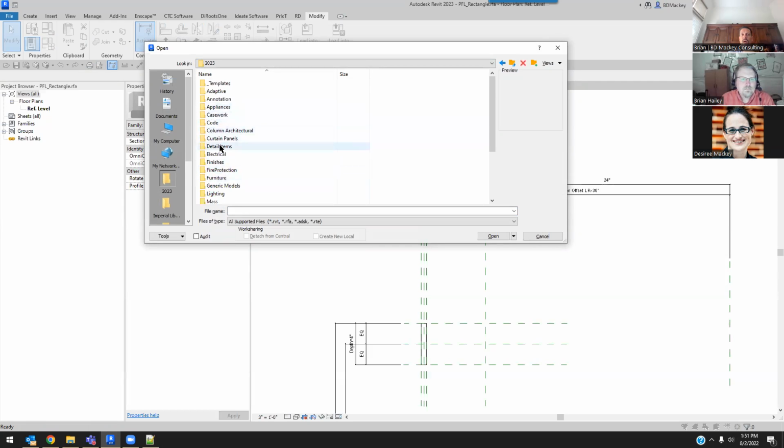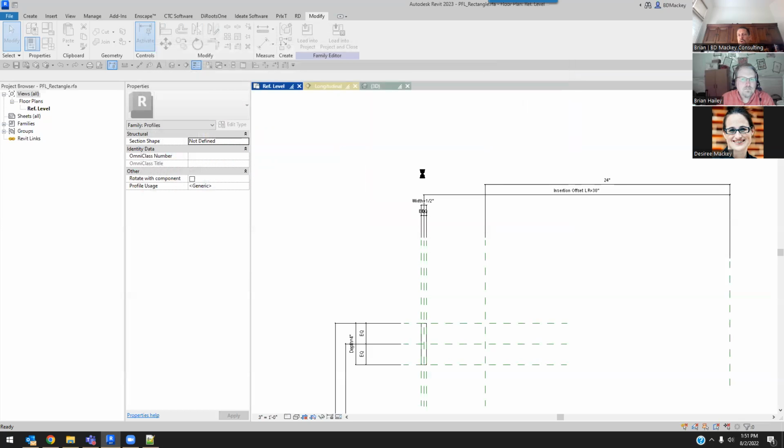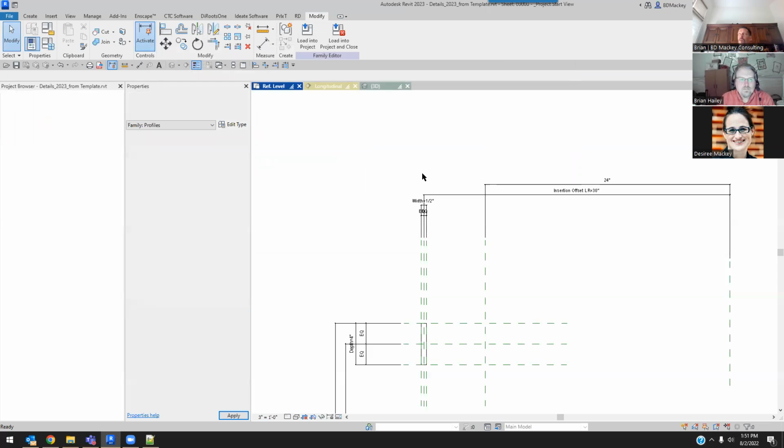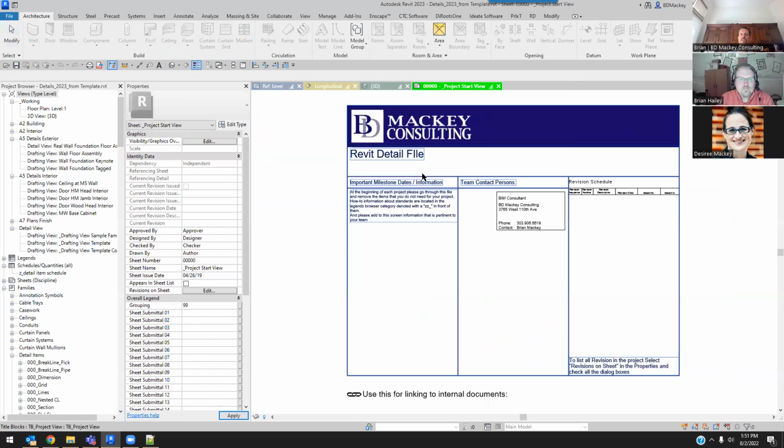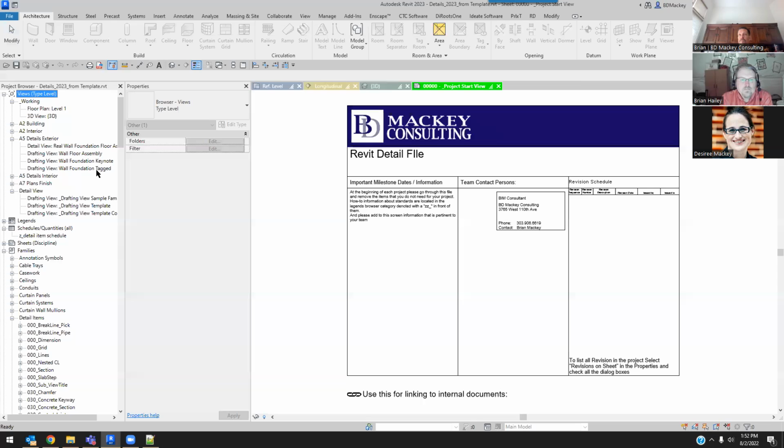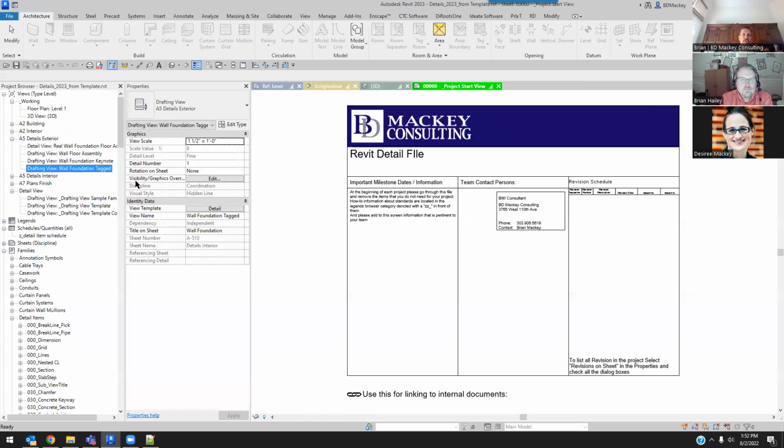The details are more than just lines, right? The example I always say, and so many people get tied up in this, and structural engineers don't fall into this as much as architects do: when I put a component down, I don't want somebody calling that component something different. I don't want somebody going in saying, hey, this is a number 5 rebar versus a pound space 5 versus 5 pound or whatever, and labeling that rebar 15 different ways. Not as bad for structural engineers as it is for architects. You'd be amazed how many times you can find gypsum board spelt in an entire project.